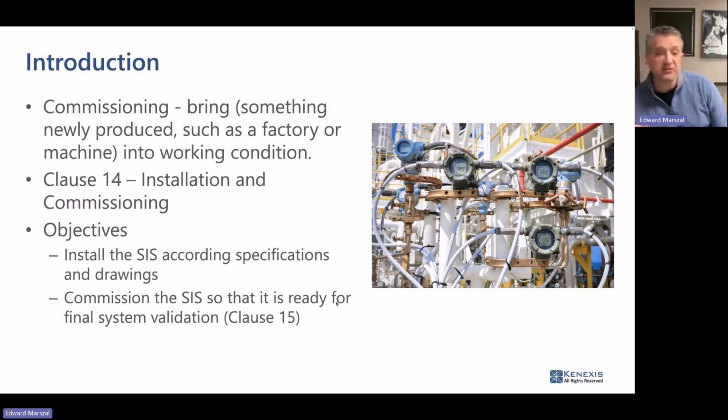Now, with respect to safety instrumented systems, which is kind of one of our core activities here at Kenexis, we're going to be following the rules of commissioning in accordance with the IEC 61511 standard. So here in the top drawer of my work shelf, I have the IEC 61511. It's never very far away from me. And if you go into clause 14, you're going to see all the rules for commissioning. So clause 14 in the copy that I have is on page 69. I've got the official IEC edition here.